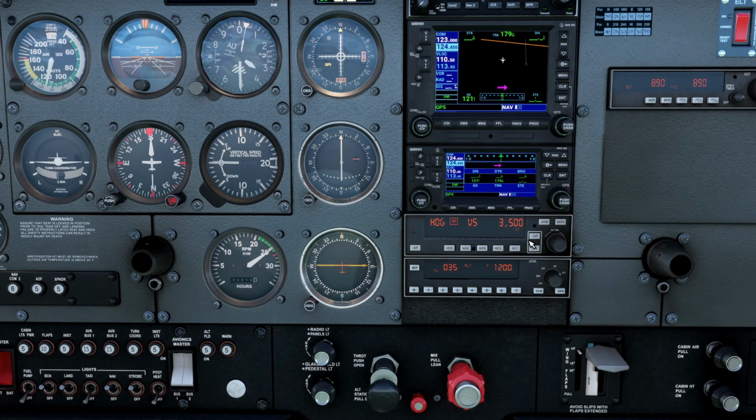This can be used in conjunction with the altitude pre-select function to capture an altitude. It will capture an altitude if the vertical speed that you set will eventually result in you obtaining that altitude. If the vertical speed will not result in you eventually encountering that altitude, then it will just continue that climb or descent indefinitely until it either hits the ground or runs out of engine power to continue the climb and stalls.